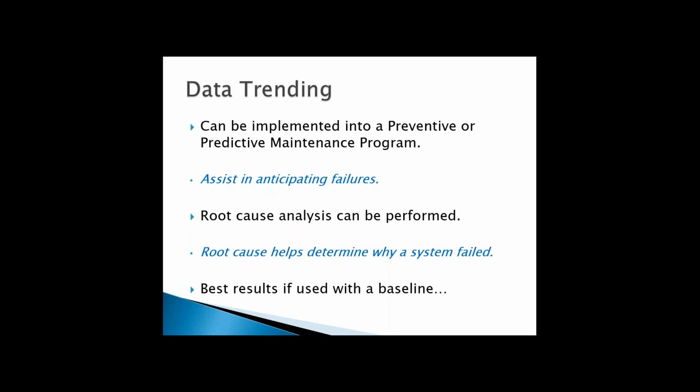To get the biggest bang for your buck for this technology or this equipment, it is always going to yield the best results if you use this with a baseline. Quite simply, a baseline means that prior to viewing anything with your thermal imaging camera, you establish a baseline, so that if you make any changes or recommendations, you have a baseline from which you started. Very often this means taking initial readings when a piece of equipment is installed, or if you're doing home performance, taking pictures or a thermal image of the structure.